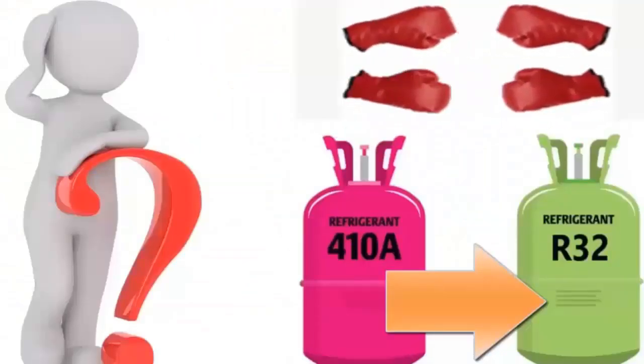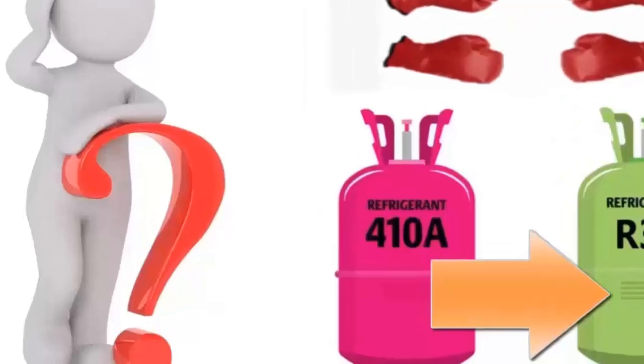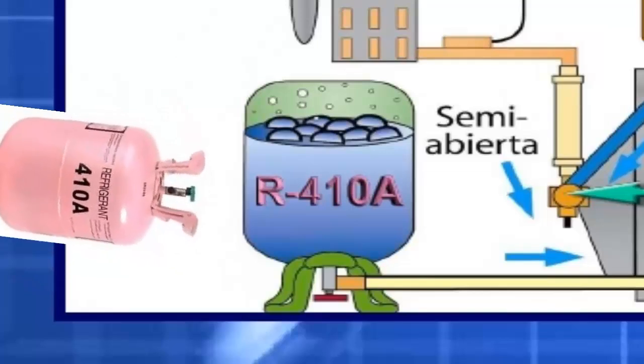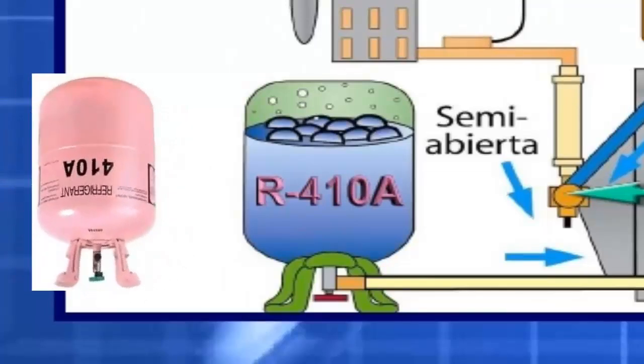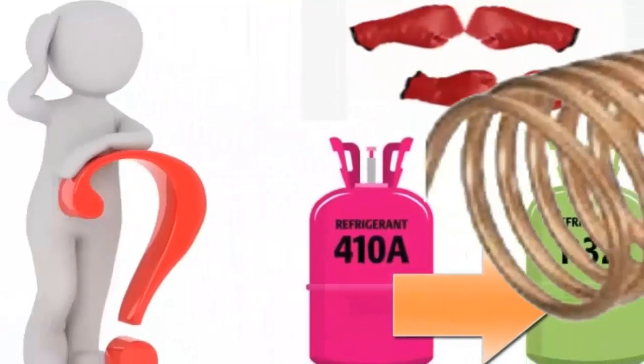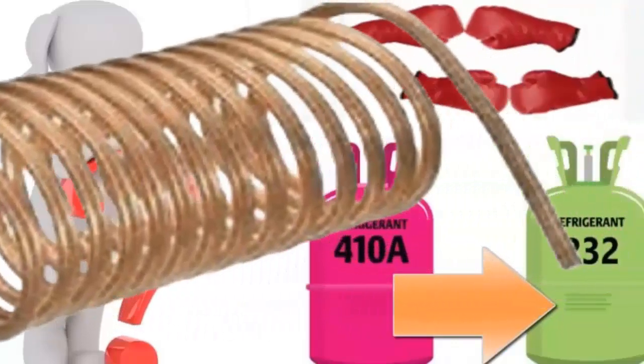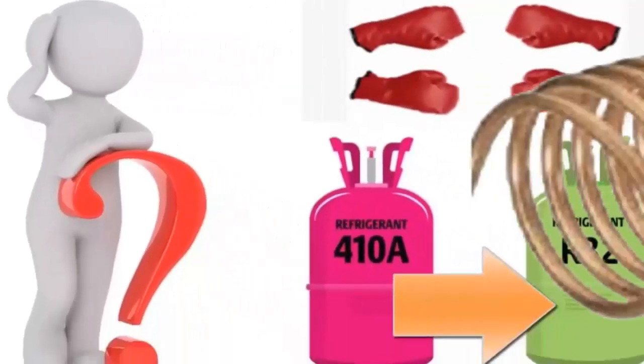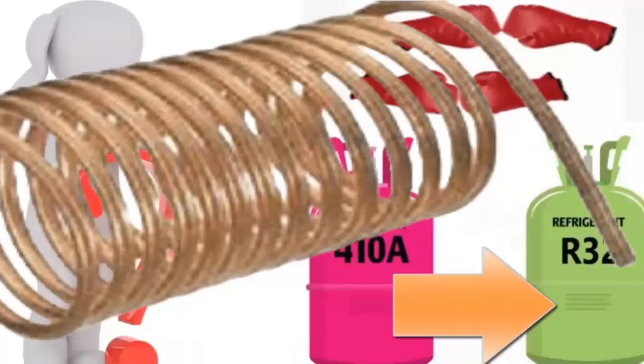F. If you decide to use R410A in a system designed for R32, the capillary tube may affect system performance due to differences in the flow properties of both refrigerants. However, you can test the system using the original capillary tube for R32 and evaluate the system's behavior. In many cases, the unit operates satisfactorily.